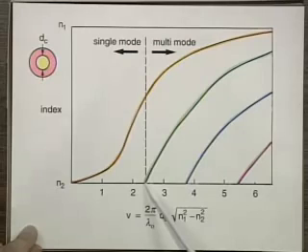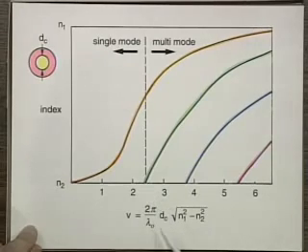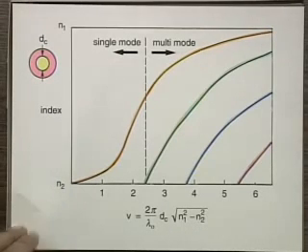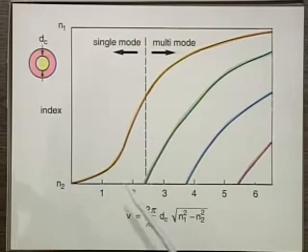In this previous demonstration, then, what we had was a single mode fiber, which means a fiber that satisfied this V number being less than 2.4 or so, because of the choice of the core diameter, the wavelength, and the difference in the indices. Now, in this next demonstration, we're going to violate this. We're going to create a V that is bigger than this value.